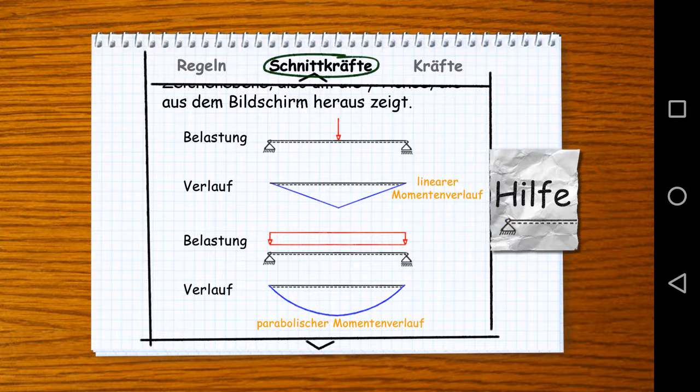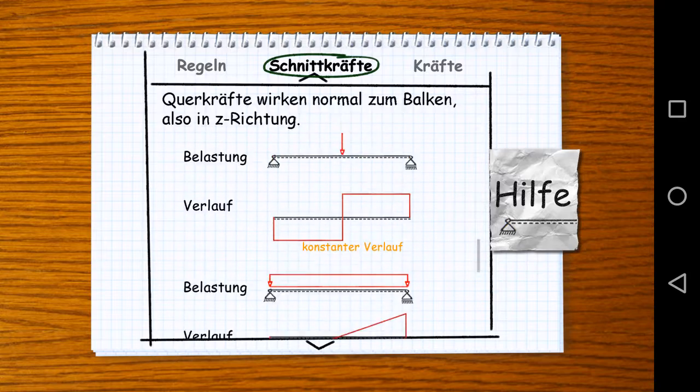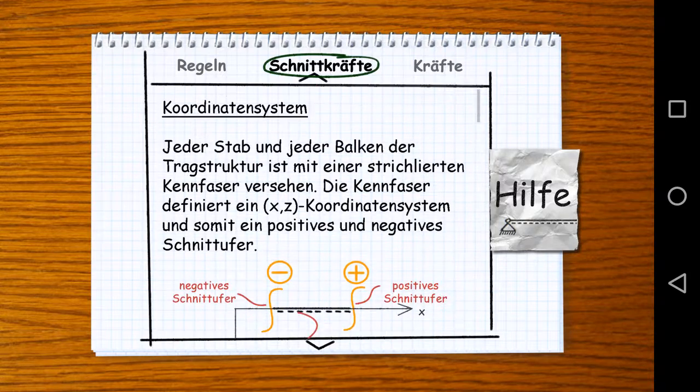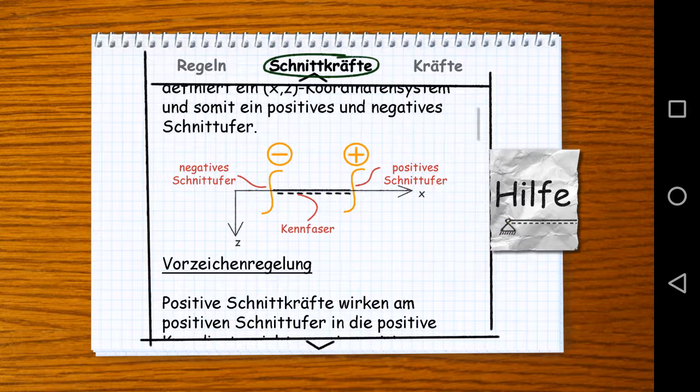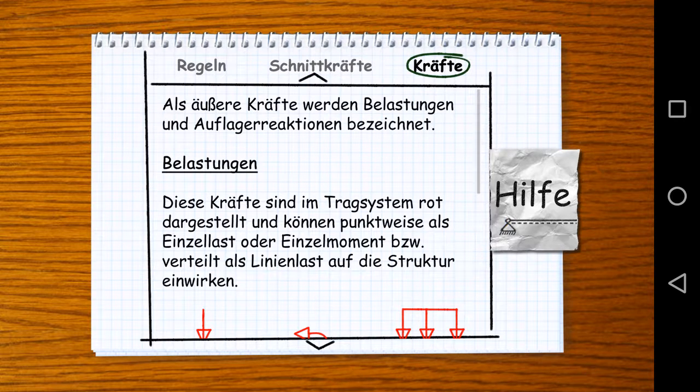So it's basically bent upward. So we have a deflection downward, but it's open to the upper side, basically. So this is a negative curvature, meaning positive bending moment. Yeah, I have other videos where I actually explain in further detail what's happening there, but that's going to be it for now.